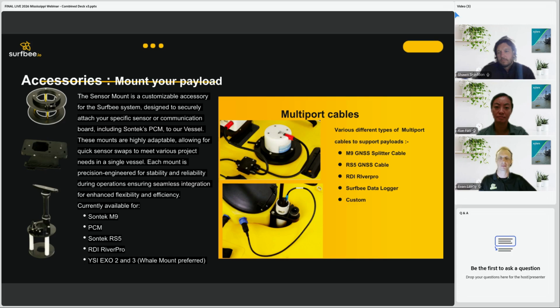This makes for a tighter integration with the ADCP, and also you have the added benefit of being able to put the GNSS heading into the ADCP, which makes the ADCP much more immune to magnetic interference and gives a reliable external heading source if your bottom track is no good.